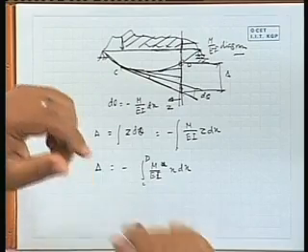And if you take first moment of area about D or point 2, whatever you can say, it will give the deflection measured from D towards the tangent drawn at A, but your measurement should be perpendicular to the initial line, okay. Right.